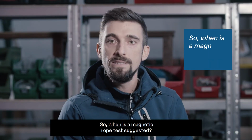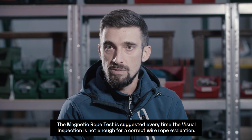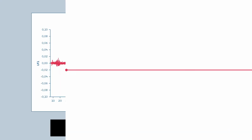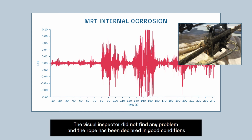So, when is a magnetic rope test suggested? A magnetic rope test is suggested every time the visual inspection is not enough for a correct wire rope evaluation. This picture shows a diagram corresponding to a magnetic rope test in a marine environment. The whole rope was covered with lubricant and it was very difficult to perform an in-depth visual inspection. The inspector did not find any problem, and the rope was declared in good condition.